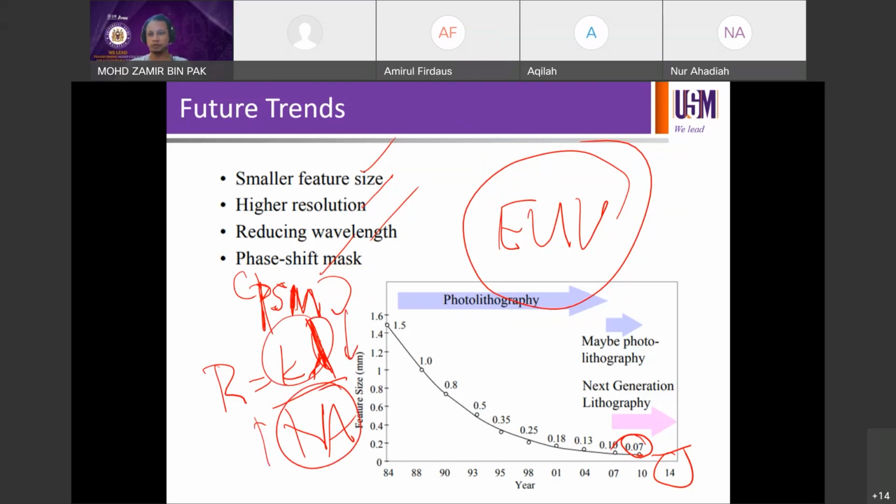So that means reducing the process factor K and reducing the wavelength, which is already at the limit as of now, EUV 13.5 nanometer as the illumination wavelength, or increasing the NA, increasing the numerical aperture of the system. So if you want to push for higher resolution, increasing the lens NA, numerical aperture, will become super crucial. You can check what the current NA of EUV is, how you measure NA, why NA, and how do you optimize NA to a higher level?